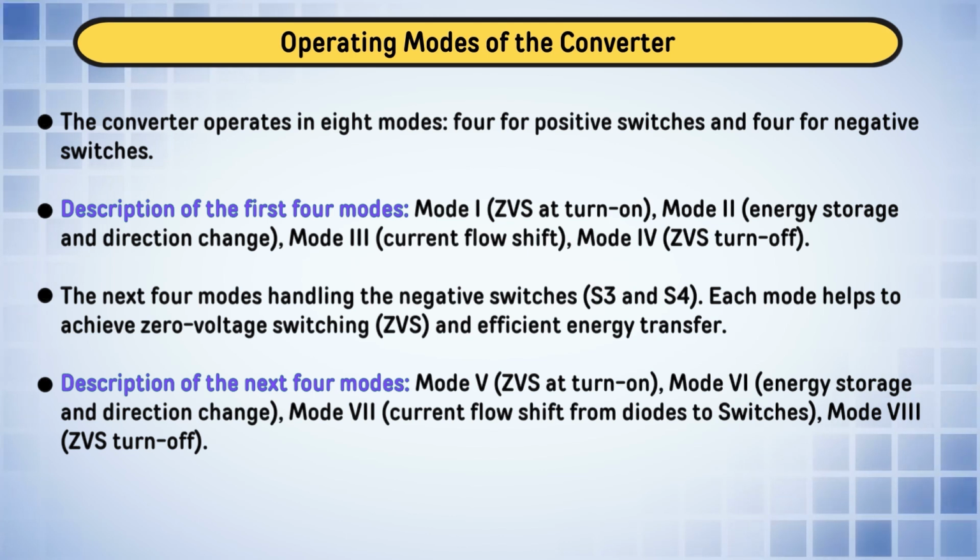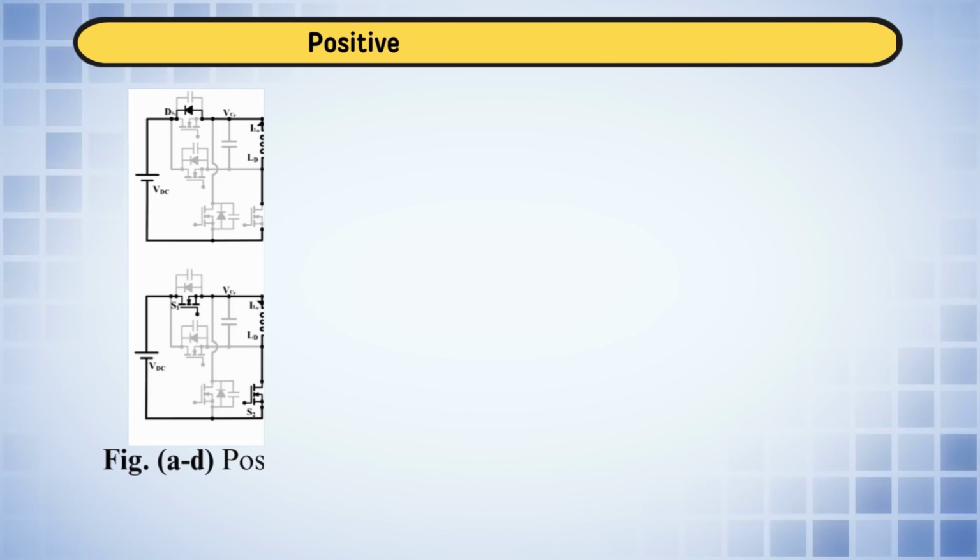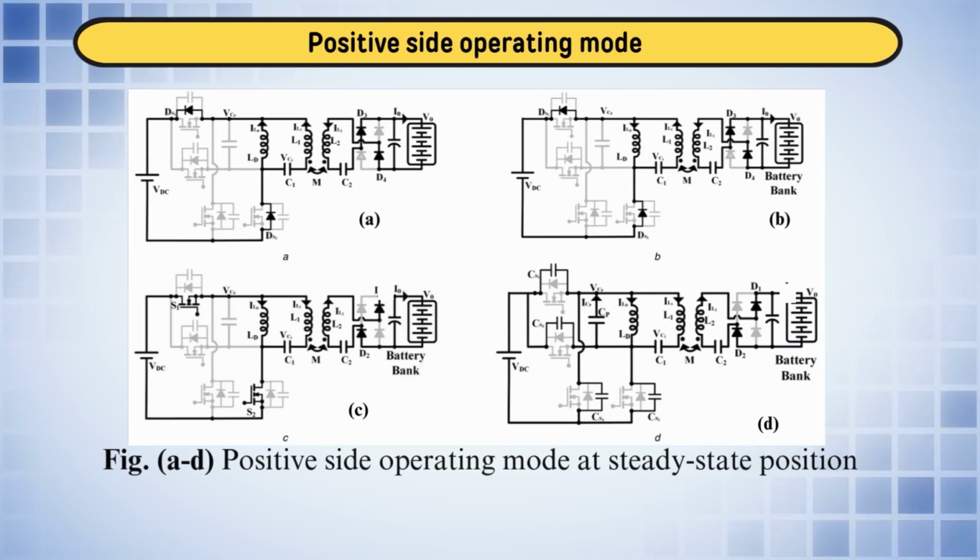maximum power is transferred at 90 degree phase shift with 0.5 duty ratio, and we have this zero voltage switching operation under various voltage ratios when the converter is lightly loaded, fully loaded, and at some medium power level. So, these are a few simulated and experimental results, and we have also shown the supply and battery side voltage here, and then zero voltage switching operations.